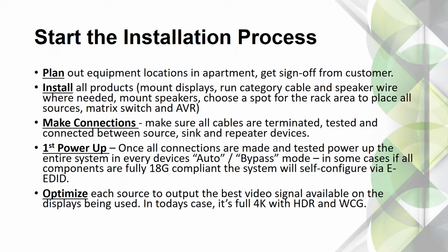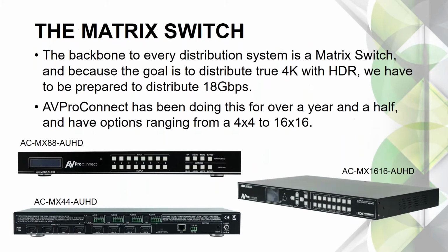But it's better to do this once everything is connected up the way it should be, and then you do have a chance of getting EDID and auto functions in the displays and the switches to get the setup at least close to being correct, and at least getting a picture and sound out of every location. So on the first power up, after everything is connected, we'll let this thing self-configure with EDID. And then we'll go in and we'll start optimizing every source to output for the best video quality available.